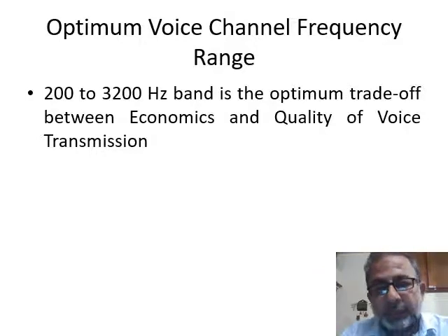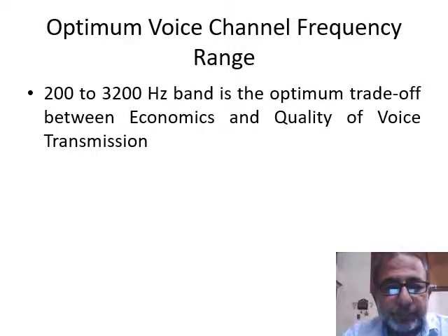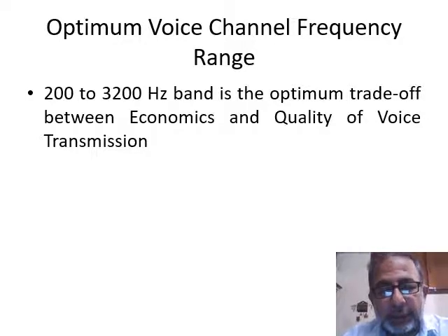But if we do not use 0 to 20 kilohertz of bandwidth to transmit, it is quite okay. Even using a 4000 hertz or 4 kilohertz channel for voice is perfectly okay, because with this much information embedded into the channel, it is quite easy to understand the speech, as well as quite easy to identify the speaker.